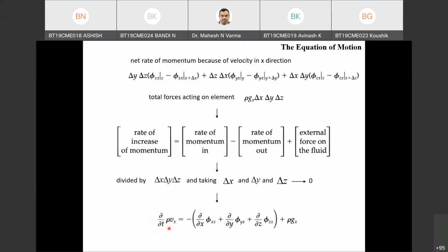Okay. Accumulation term is accumulation of momentum, accumulation of momentum in a shell momentum balance. It is delta x into delta y into delta z into rho into del Vx by del t. By dividing delta x, delta y, delta z on both sides, after substituting in the shell momentum balance, I got the equation.